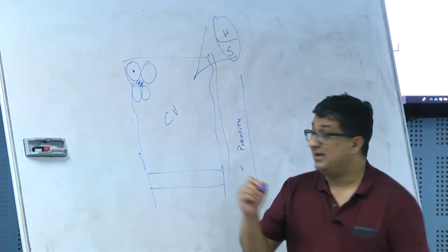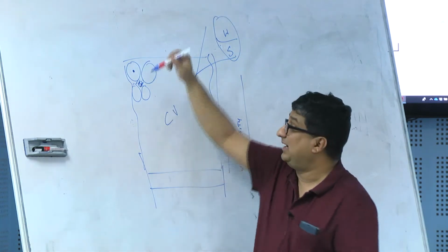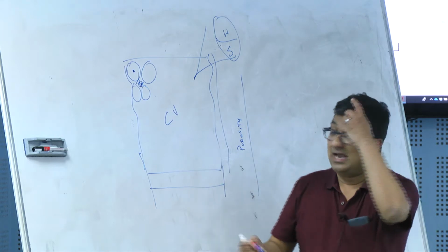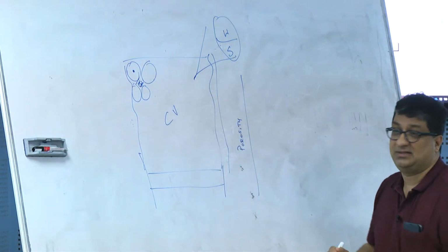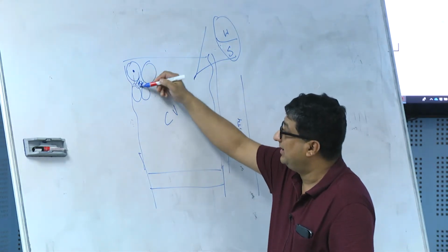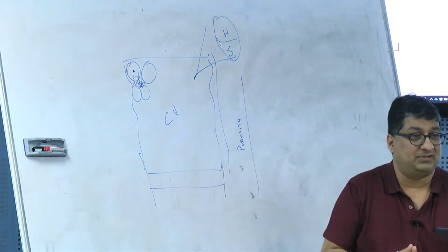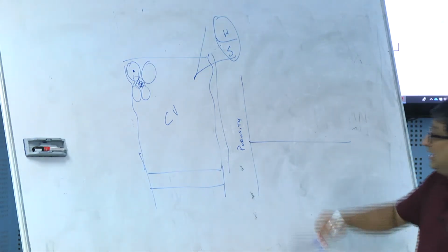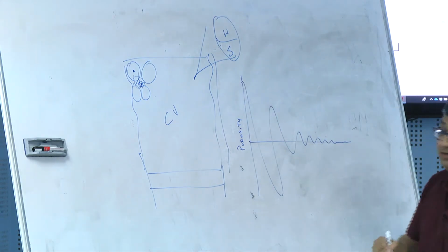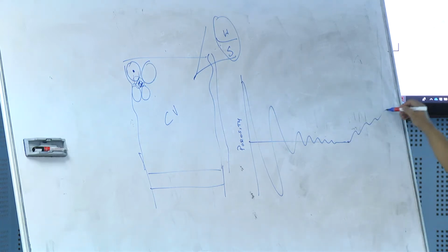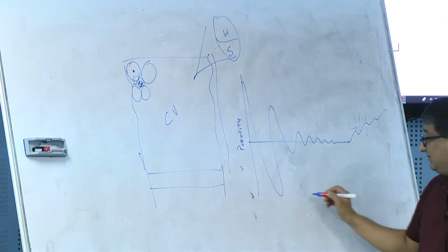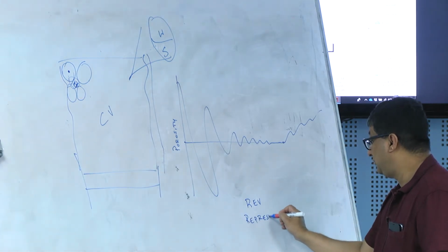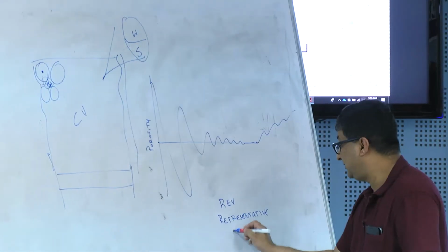On the other hand, if I'm taking a sample and I land here, all I'll see is a grain, I don't see any water, so my porosity is obviously 0. As I increase the size, I'm going to see a little bit of sand, a little bit of pore space, and so on and so forth. So if I plot porosity versus distance, it fluctuates quite a bit and then it becomes constant. Then it starts to increase again. So this is plotting porosity versus what we call the REV, or representative elementary volume.